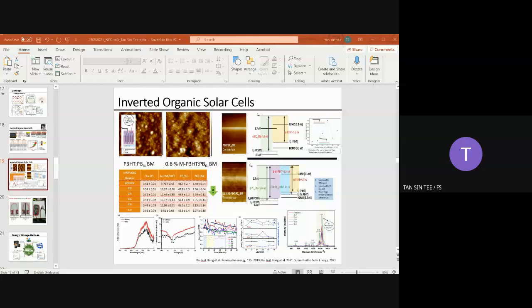For this sample, our nanostructure is the zinc oxide nanorod, used as the electron transporting layer. What we want to optimize is the conductivity and thickness of the electron transporting layer. We do the experiments, always taking at least 10 times for one of the devices, and then we alter different thicknesses of the zinc oxide nanorod.